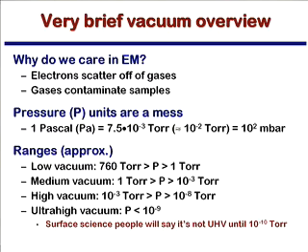The way to kind of remember is there's about a 10 to the minus 3 difference, so if you read 10 to the minus 3 Pascal, it's about 10 to the minus 6 torr. But again, it's a problem. Millibar and torr scale sort of together. Again, other vacuum gauge companies will use millibar.